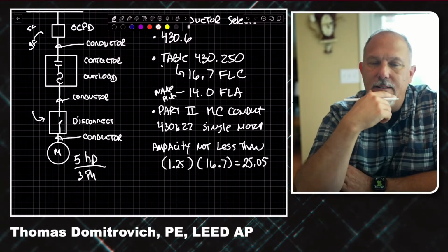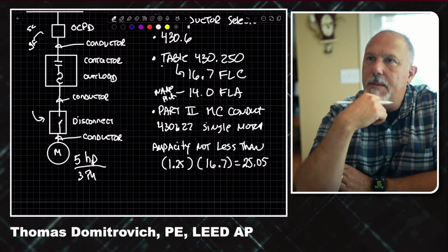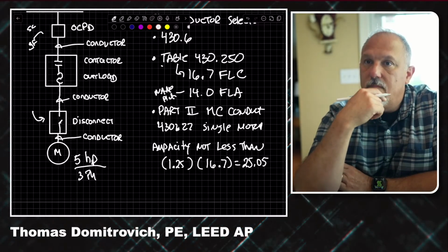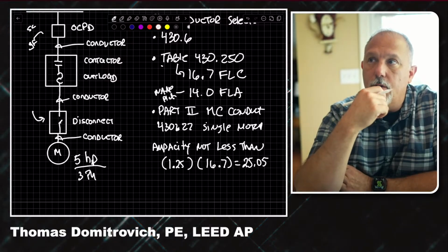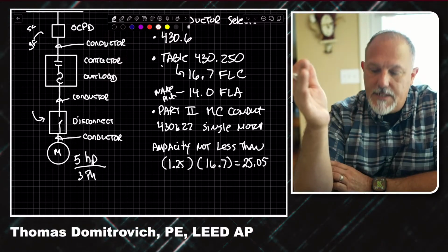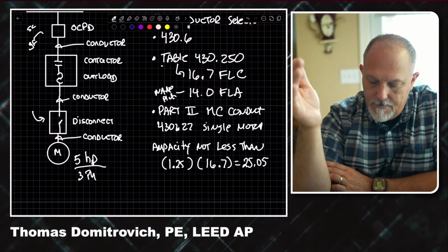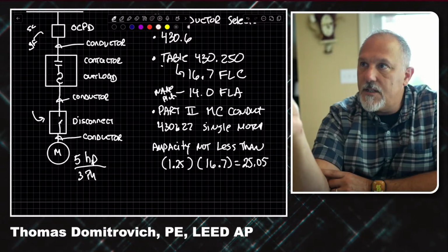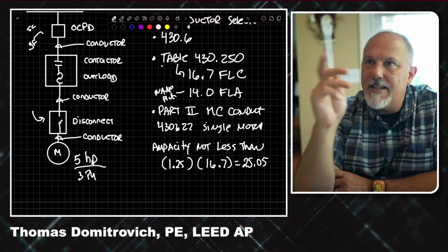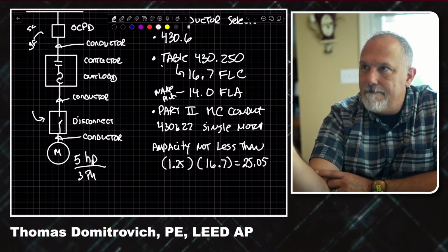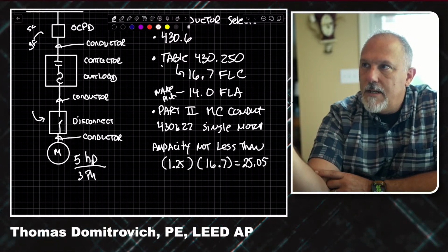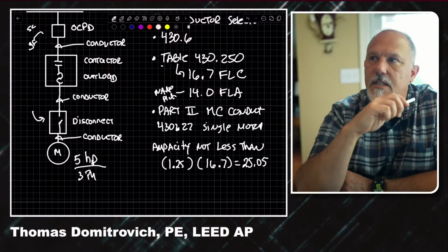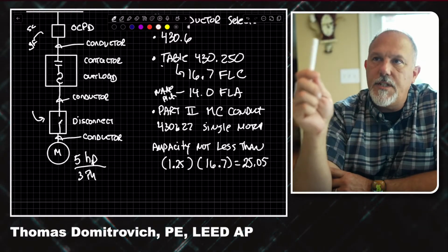This is bothering me, Ryan. This is bothering me because ampacity is not a 110.14 thing. And I know my motor, I know I have 90 degrees C insulation conductor. I can't go to the 75 degrees C column for this because it says conductor ampacity. It doesn't say termination. Termination will get you to the 75 degrees C column. 110.14 reference will.